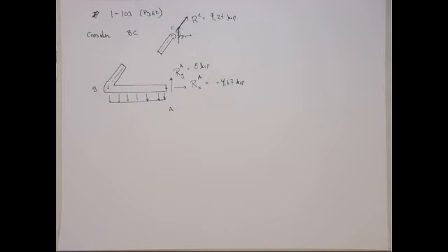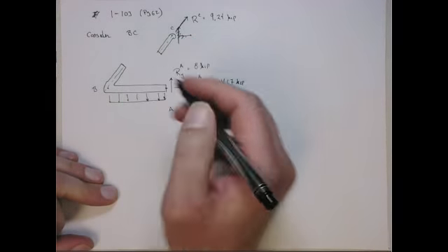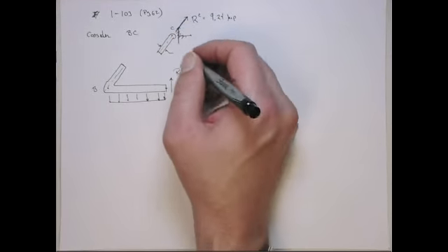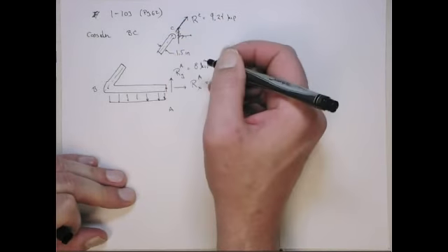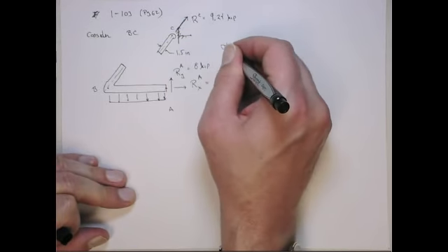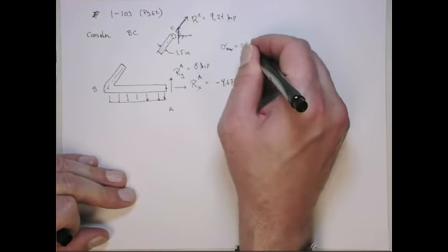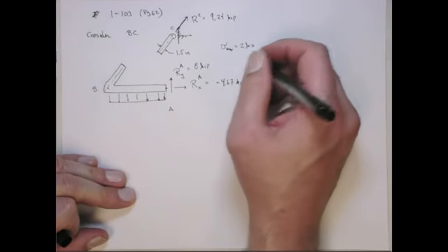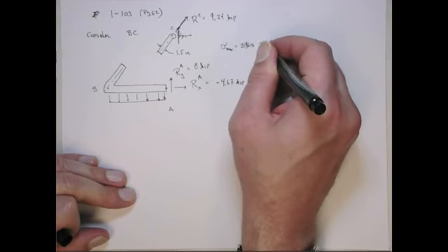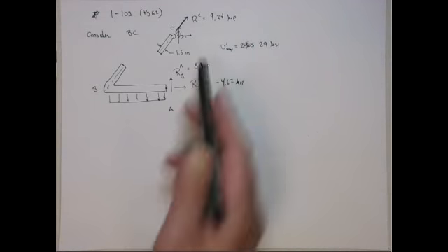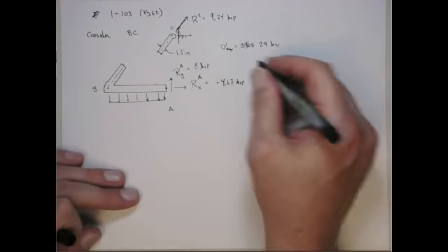All right, so first let's look at sizing BC. So I know in BC this dimension here is given at 1.5 inches. And I also know the maximum allowable stress in element BC is 29 KSI, okay? So that's the maximum allowable average normal stress. Tension, compression, obviously. In this case, we already know that it's acting in tension, all right? So we can figure that out.